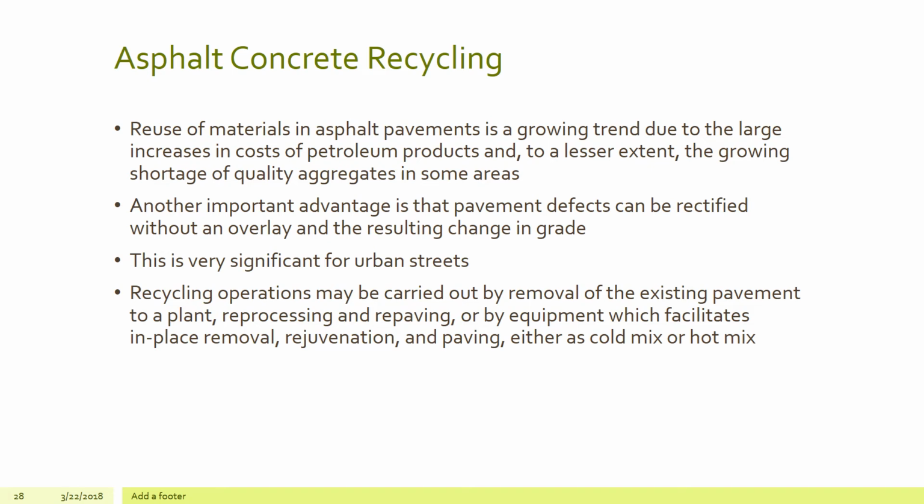Let's take a look at asphalt concrete recycling. Reuse of materials in asphalt pavements is a growing trend due to the large increases in the cost of petroleum products and, to a lesser extent, the growing shortage of quality aggregates in some areas. Another important advantage is that the pavement defects can be rectified without an overlay and the resulting change in grade. This is very significant for urban streets.